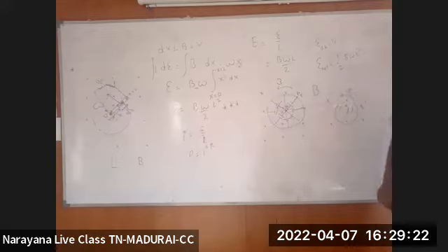Here also, between the center and any terminal point, what is the EMF induced? What is the EMF induced between the midpoint of the disk and any terminal point I am asking? Same thing: half B omega R square. To glow a bulb or to function any kind of device, you have to connect those terminals between the center point and the end only.